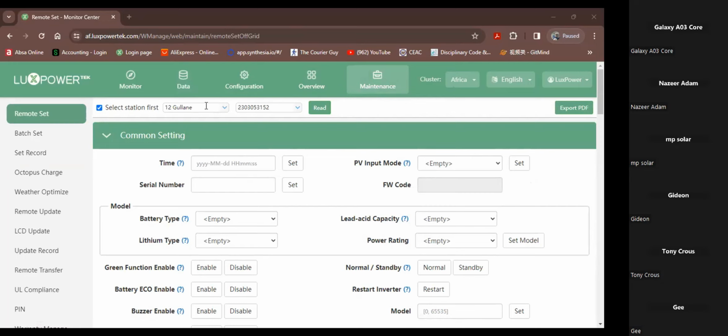And Jonathan wants to know, may I get clarity on the difference between 385 volts and 480 volts that is mentioned on the SNA 5K? Which one of the two should I be mindful of when I'm adding panels to my system? Is it one for the panel's VOC and another for VMP, or is it one per the MPPT and another for the bridge? When I ask in the Lux support groups, it just causes a lot of debate.